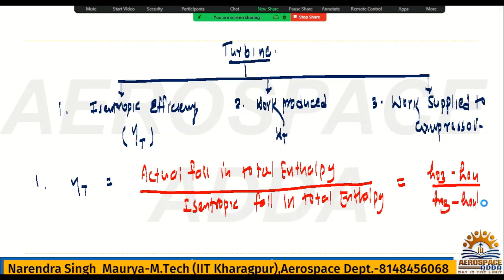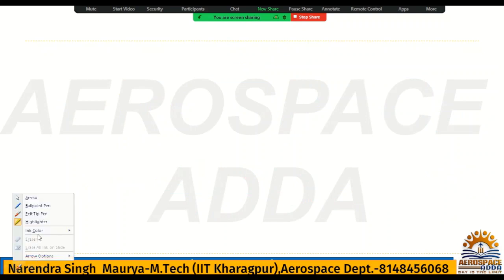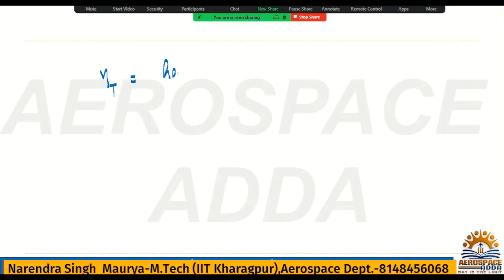Okay. So if you write, this is the first point only I am saying. Turbine efficiency is (h03 minus h04) divided by (h03 minus h04 dash).